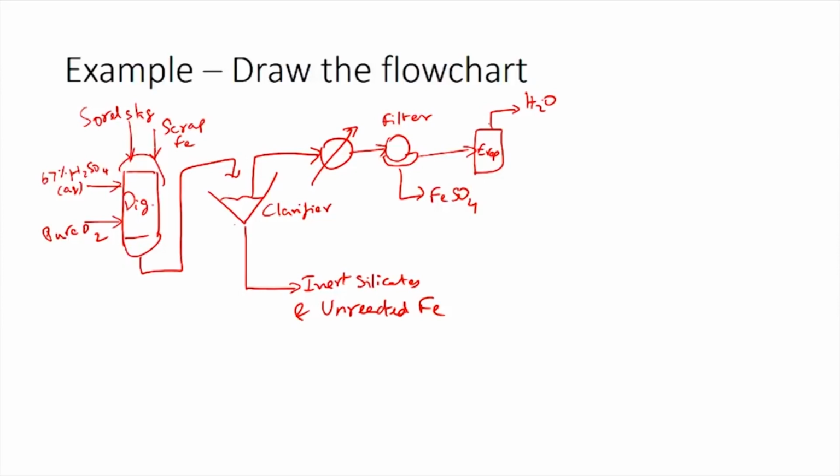This has also been given as a hot air dryer. A hot air dryer is one where you have hot air entering the dryer in addition to the wet component, and this hot air helps in drying the component. So, you also have air entering, and you would have air carrying water leaving the system, a wetter air leaving the system.